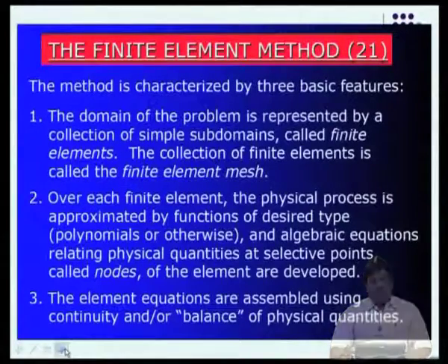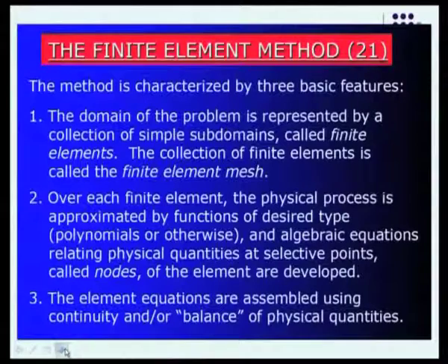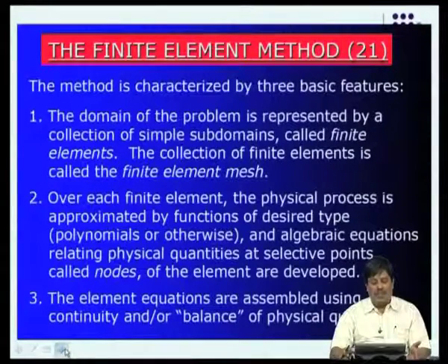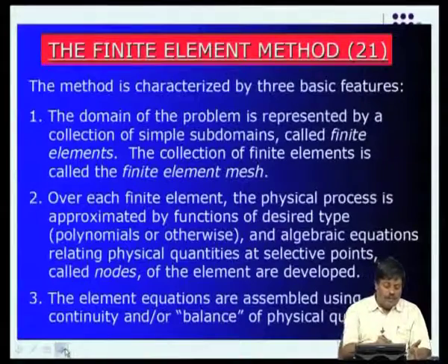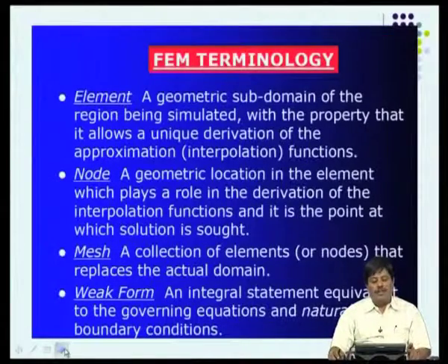The element equations are then assembled together using the principle of continuity of the dependent variable and its gradients, or the balance of forces of physical quantities. Some of the FEM terminologies: what is an element? An element is a geometric subdomain of the region being simulated with the property that it allows a unique derivation of the approximation functions.